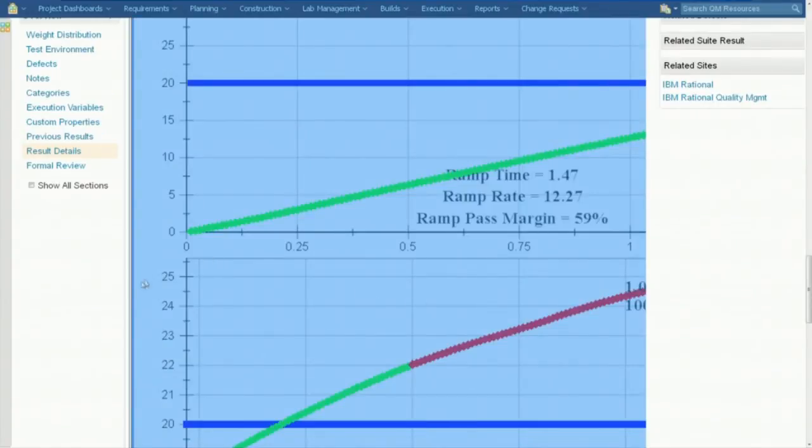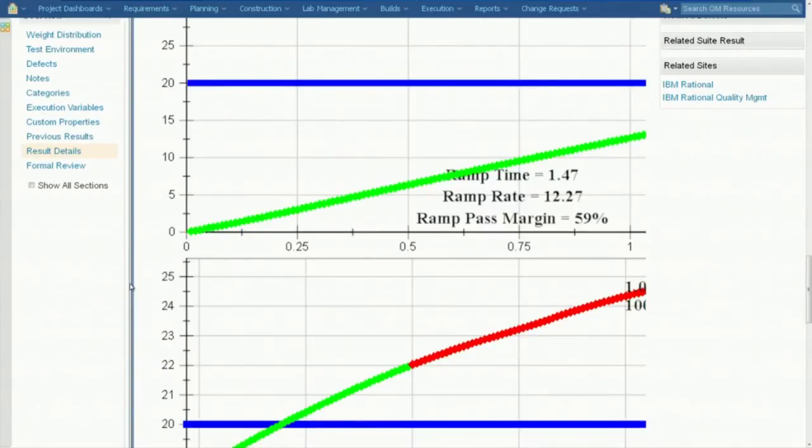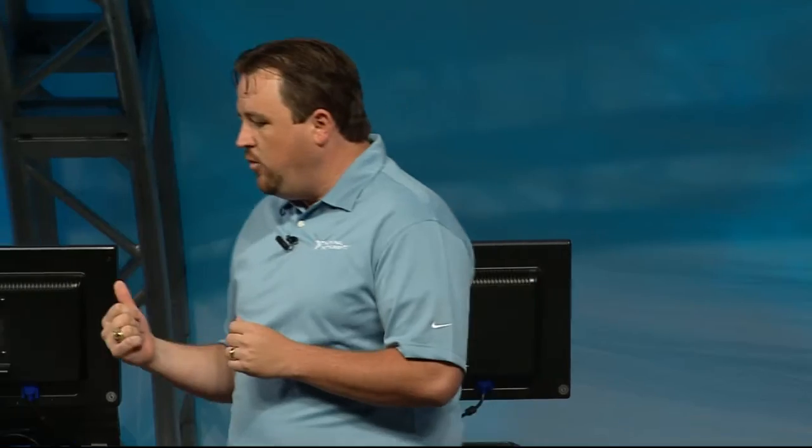So it looks like in this particular case that we have an issue in the software. It's allowing the vehicle to exceed the speed specified in the requirement for that configuration. So let's fast forward a little bit for the sake of time. Assume the software engineer fixes this defect, then what happens? Well, as you know, when you revise software to solve one defect, it's quite possible to create others in the process. So therefore, any requirement that's been validated previously with the old version of the software must be revalidated if it's possible it might have been affected by the software change.